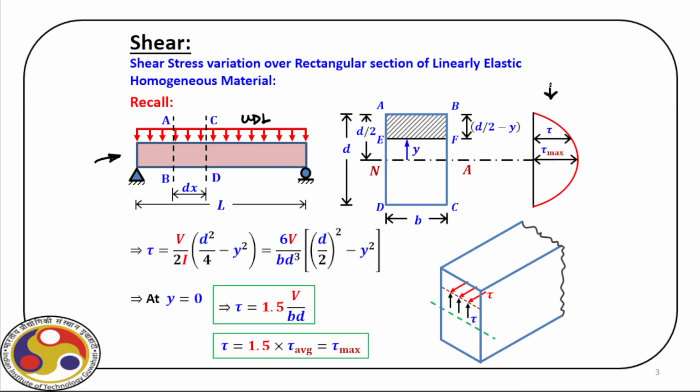So this is the shear stress distribution at the section level, and that shear stress distribution is governed by this expression, which is effectively tau is equal to VQ by IB. Obviously at the topmost fiber and the bottommost fiber tau is 0. And then as we go deeper, at the middle we have the maximum value of tau here.